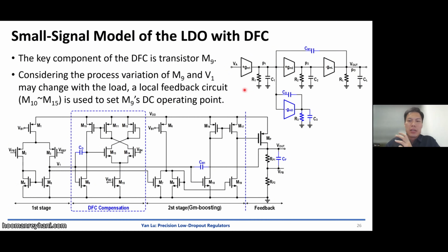In the capacitorless case, if this LDO doesn't have an output capacitor, if we don't connect an output capacitor, this LDO will shift to the internal pole dominant case, right? Then the EA output, or the differential amplifier output, will be the dominant pole with Miller compensation. Okay, and yeah, that will be the case.